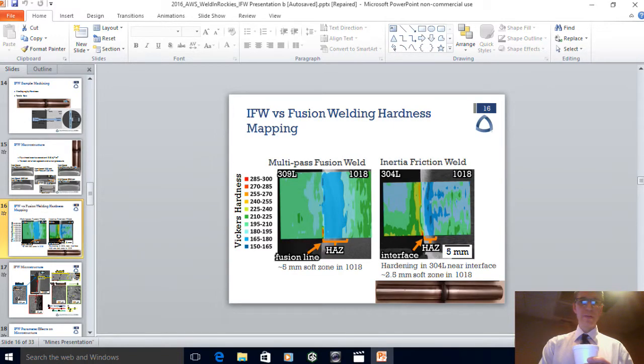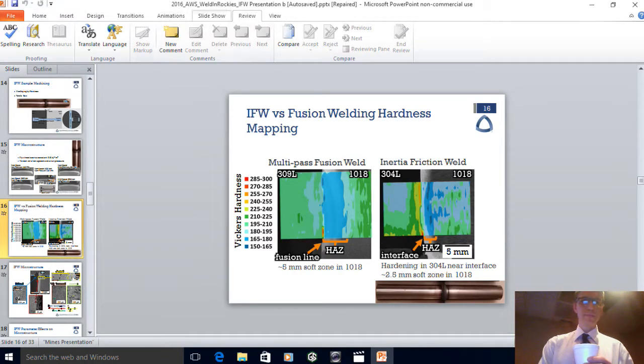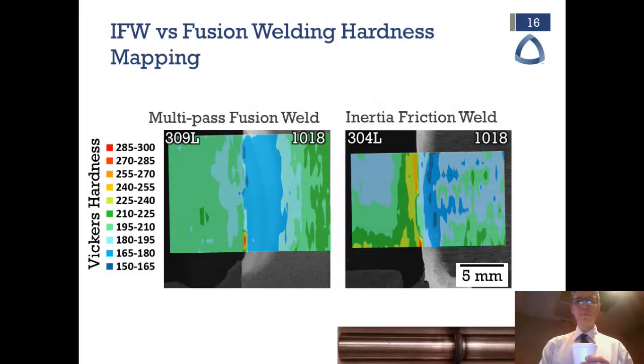Next question. Is that an actual fusion process, or is it an adhesion process? It's a solid state welding process. You get the same problem with friction stir welding because you're doing something in the material that makes it almost behave like a liquid, but it never gets to the melting point.